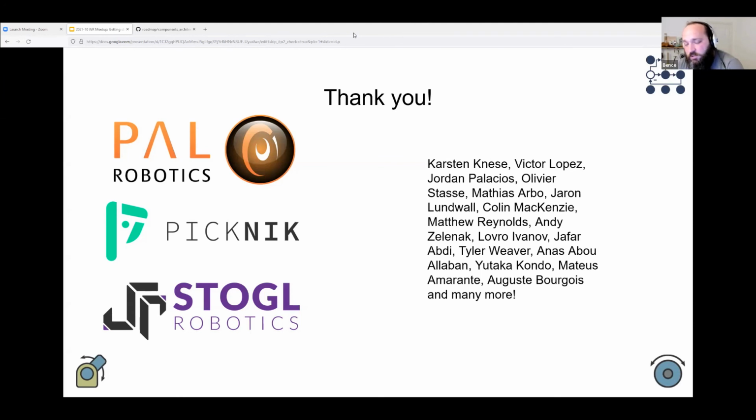So yes, ROS control is using what we call the control toolbox, which is not MATLAB, but much simpler. It mostly has a PID class, and we're using the same code base for ROS2 control as well. It's a very simple C++ class, just does your good old PID. So have a look at the forwarding controllers. Again, the caveat is we're not fully aware yet of the adoption, so maybe some of that code may not work as you would expect, but definitely give it a shot and let us know how it works out for you.